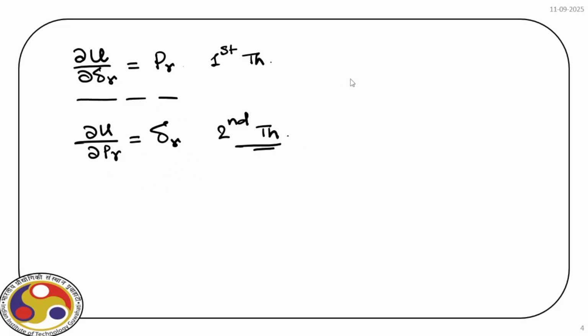Okay. So at any given point, for example, if we consider a beam, and at any location of the beam, if we want to find out the displacement, we put a dummy load there and find out the total strain energy, then differentiate that with respect to the dummy load, and ultimately we put that dummy load equal to 0, then we get the displacement.